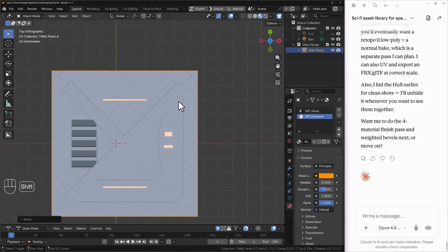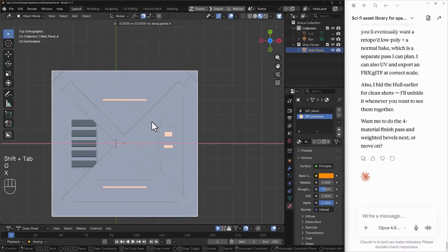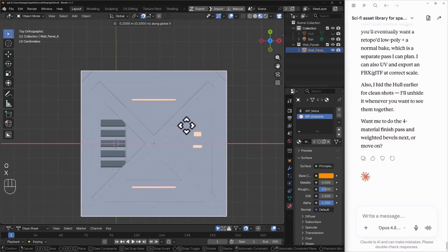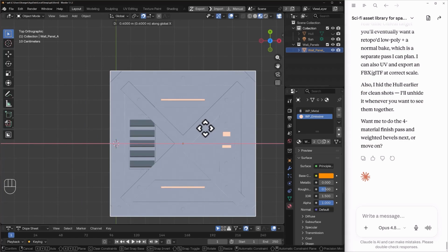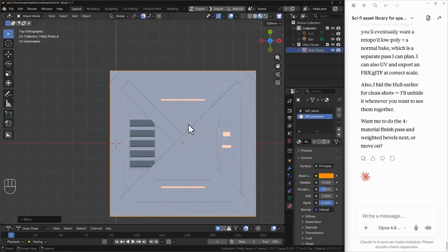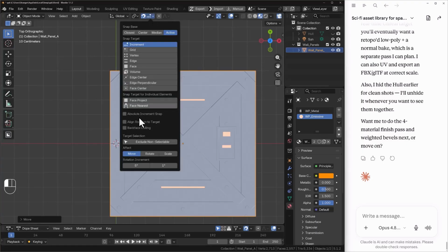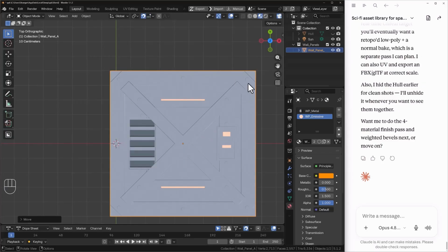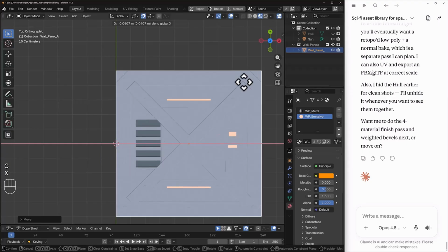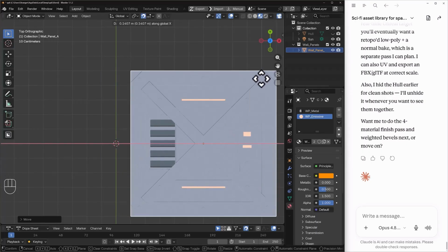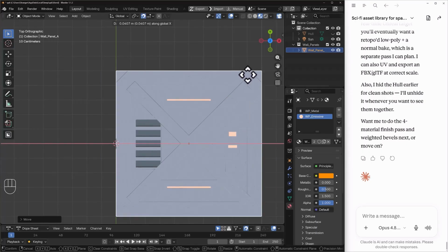So let me activate it once more. Grid, and look at it. It snaps 1 unit of the grid, but it's not absolute to the grid. But right now, if I go and click on absolute increment snap, see what it does instead. So let me press G and X. See, automatically it moves it absolutely to a grid unit.